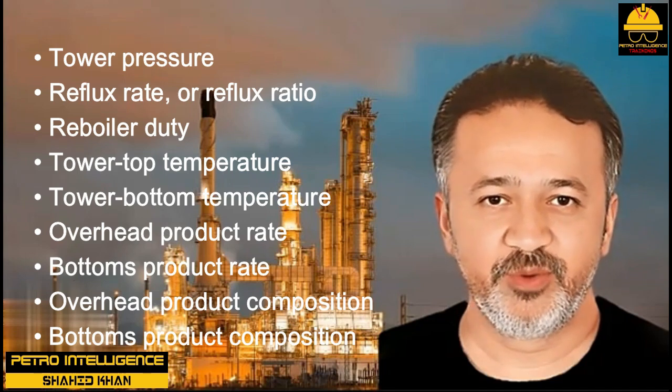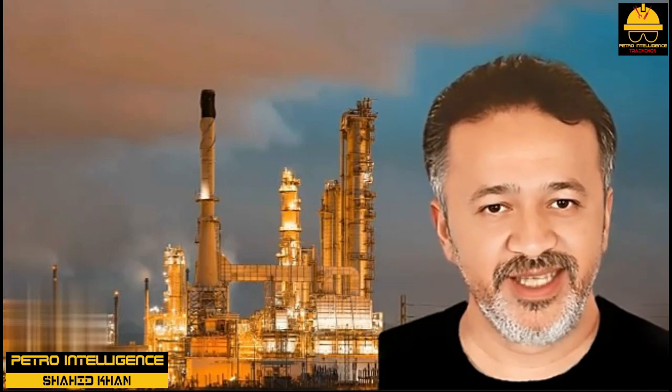The prior discussion assumes that the feed rate, feed composition, and heat content of the feed, that is enthalpy, are fixed. My purpose in presenting this review of the phase rule is to encourage the routine manipulation of tower operating pressures in the same sense, and with the same objectives, as adjusting reflux rates. Operators who arbitrarily run a column at a fixed tower pressure are discarding 1/3 of the flexibility available to them to operate the column in the most efficient fashion. Moreover, this is true regardless of whether the objective is to save energy or improve the product split.